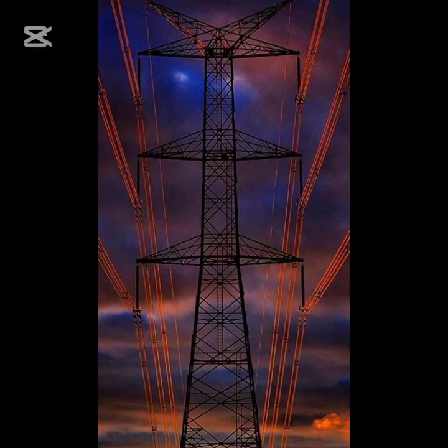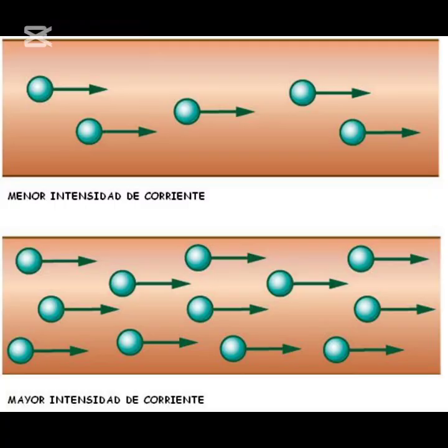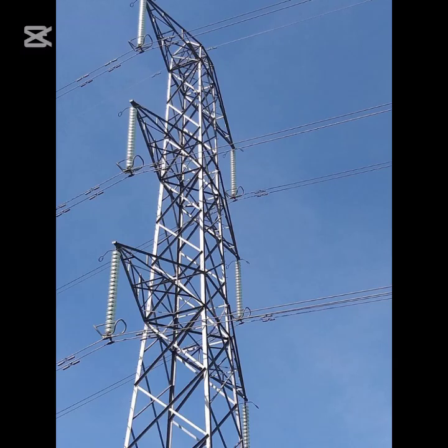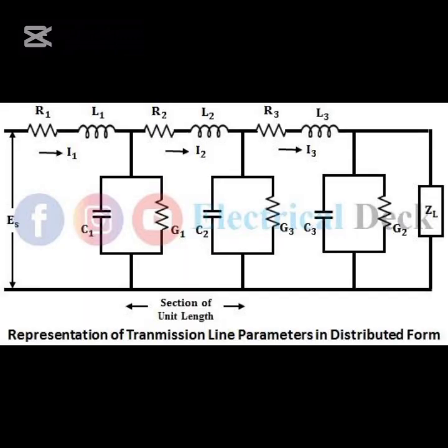Note that resistance of transmission lines increases as distance grows. To reduce this, use allowable-sized conductors and high-conductivity conductors. This property of transmission lines is the simplest. Now that we've explored how resistance impacts transmission lines, let's move on to another crucial property: the inductance of transmission lines. In the medium and long transmission lines, inductance is more effective than resistance in value.